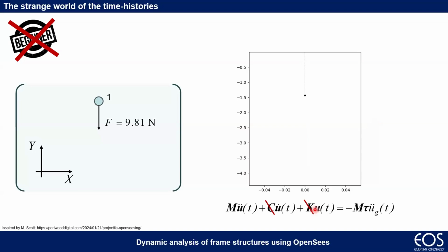Time history is a great tool. In OpenSees, they are easy to set, they're easy to analyze. You don't have to care about integration. You don't have to care about a bunch of stuff, okay? With just one line, you can declare Newmark instead of writing lines and lines of Newmark integration, okay? You can run nonlinear analysis that is pretty complicated with time history, okay? But be careful. Otherwise, you can have stuff like that, which doesn't have any meaning from a structural point of view, okay?